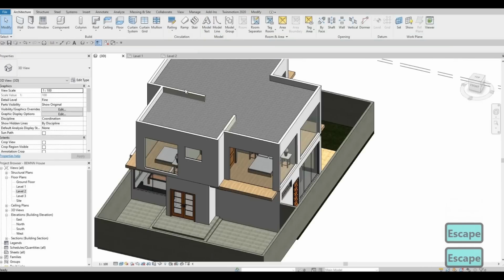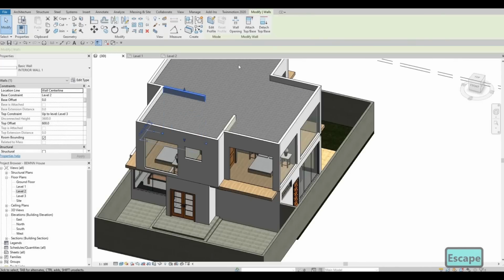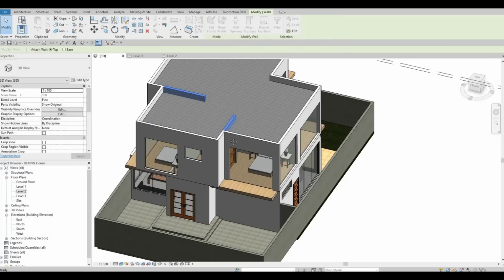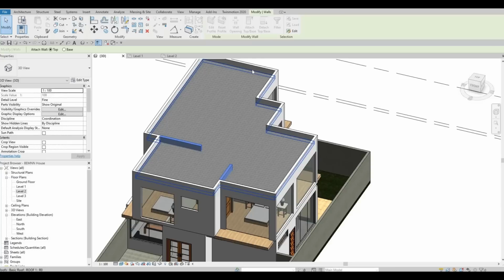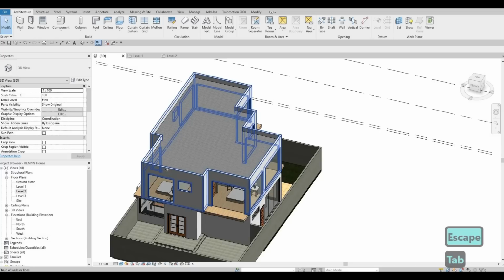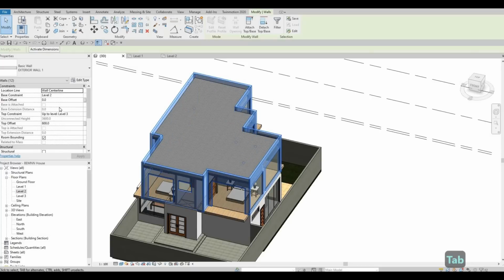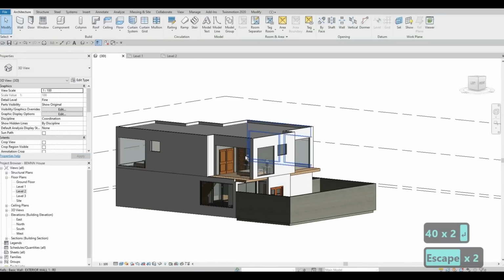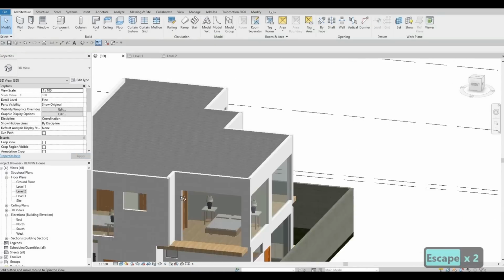Now when we go to here, we could basically pull this down. So select here and select there, click attach top base, and then select on the roof. It will disappear. And then now you can select all the exterior wall again, and you can manipulate from 400 if it's too high on your liking. So it will look like that.